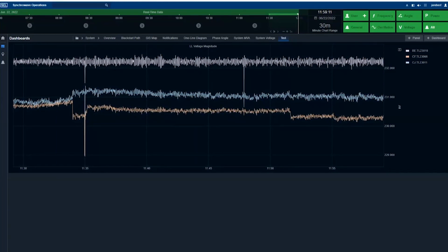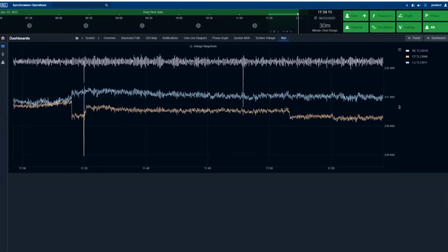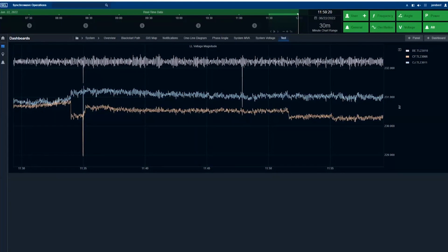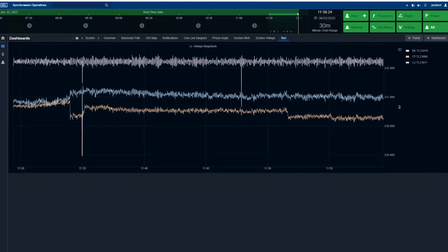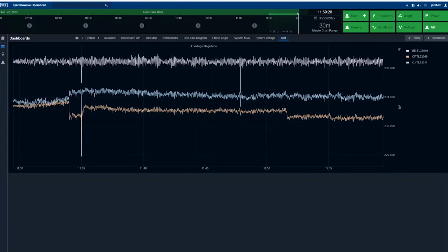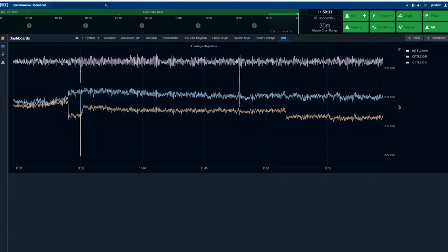We've just seen over and over again, having the current measurements for the lines and those three-phase bus measurements become very valuable to utility partners we've worked with. And the last item, I know I'm going on here, but if you're deploying a new system, when you do deploy, please wire in the circuit breaker statuses as well along the line.